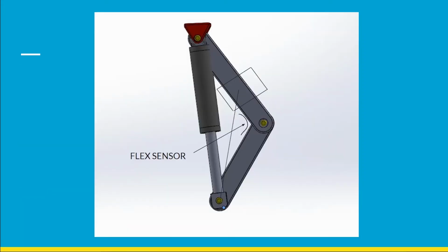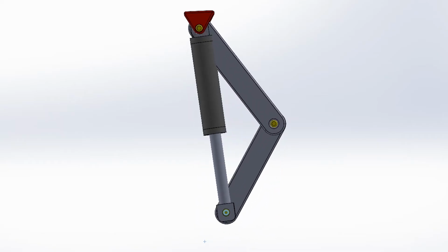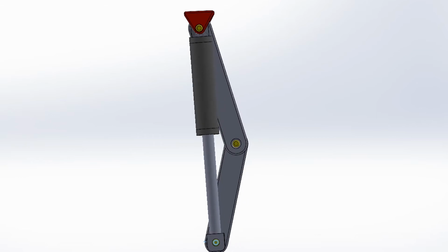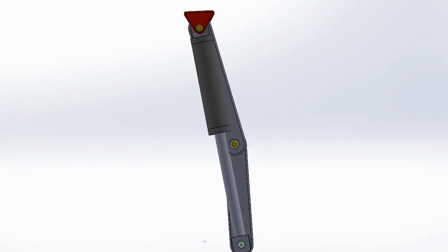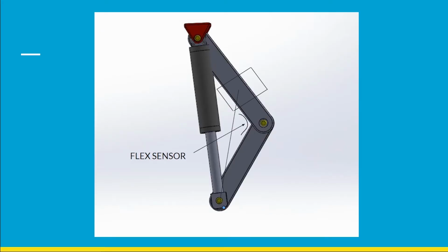Now what the above statement means is, we have a motor present exactly at the center of the thigh, which is being used to lift the leg by means of a string. When the motor is on, it is providing us with the lifting force. Now what happens is, after the leg reaches 25 degrees, the flex sensor directs the motor to turn off, while the hydraulic being used helps in providing damping.